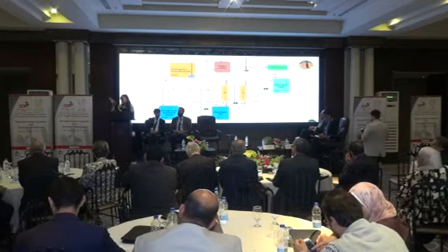This is a way that you can use the water, as you said, with anti-scaling, for the wellhead. This is great and right. But if you want to throw this water into the sea, you cannot discharge it with 40,000 ppm or more. This is according to the environmental laws. It should be up to 5,000 ppm. This is the right way to get rid of this water.